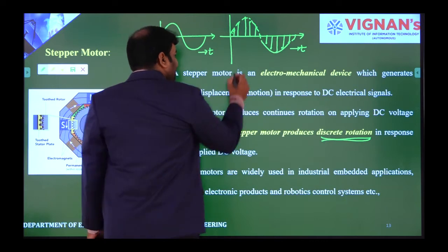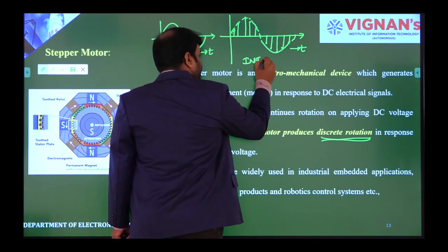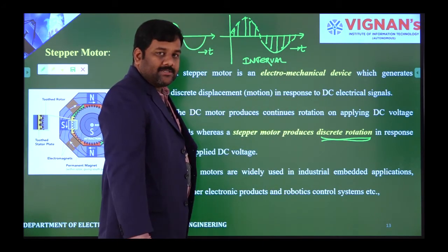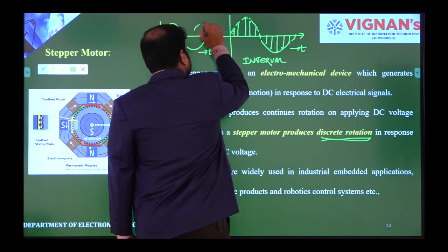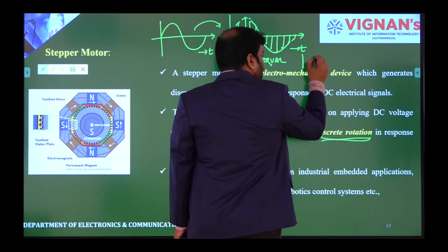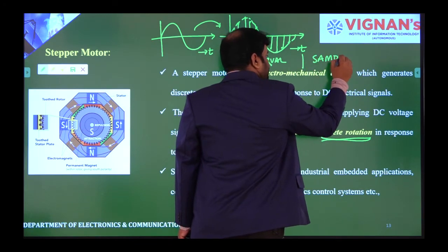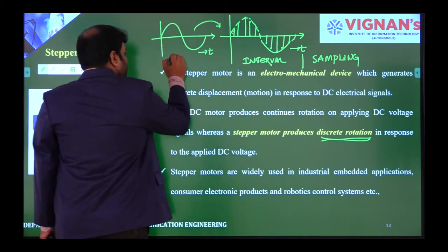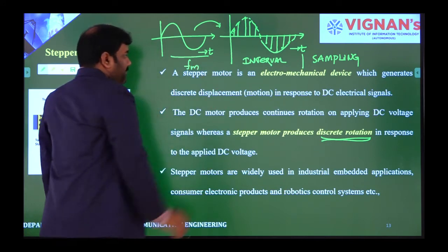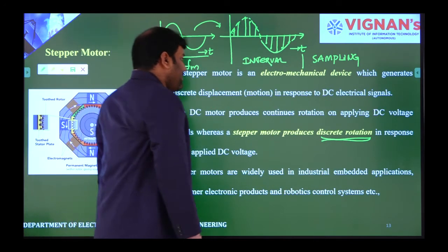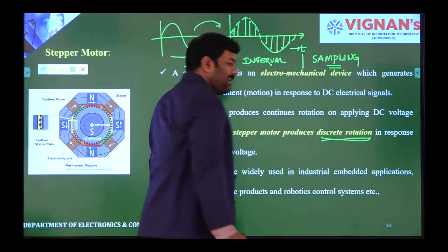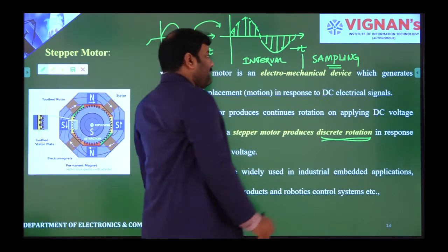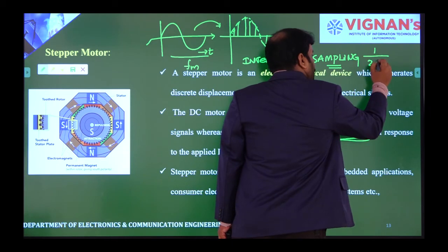Means at a specific interval basis it has been segregated into discrete parts. So from this, a discrete signal is possible by using sampling only. Sampling means, I have an input signal having a frequency of FM, like a modulating signal FM. Whenever I am doing sampling, I need to cut the entire sinusoidal signal, or message signal, or input signal, with 1 by 2 FM.